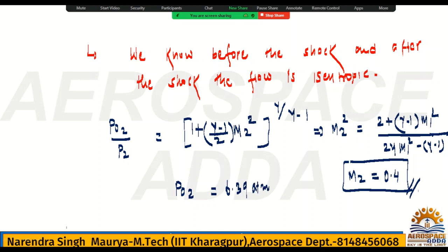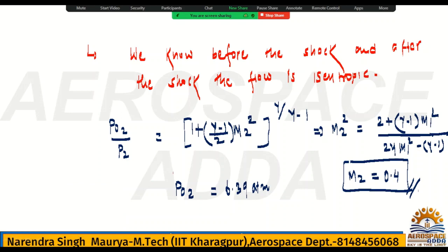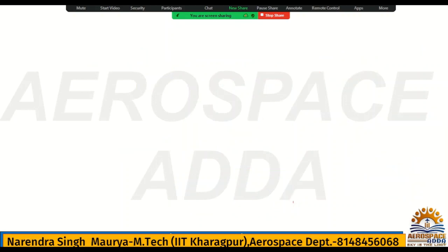Okay, this is the total pressure. 6.39 atm, all right. P naught 2 is the total pressure behind the shock. Now total temperature, how to get that? Total temperature.